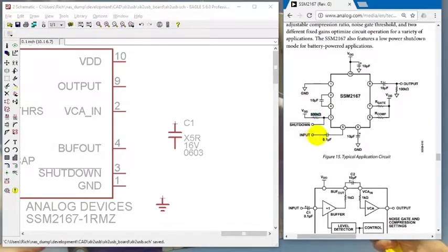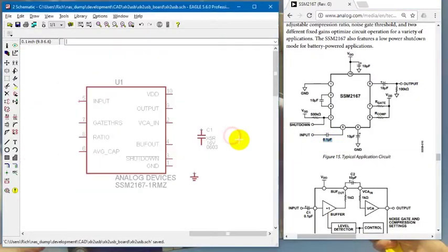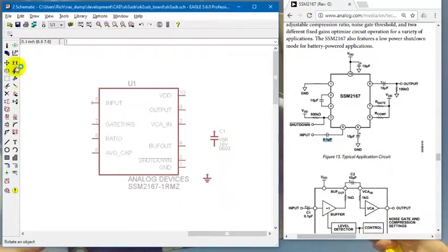Let's hit a couple of more. I want a coupling capacitor on the input side, which is pin 5. And I'm gonna cheat a little bit, and I'm just gonna copy this guy, because I'm gonna use the same size one. And this will give me an opportunity to play with a couple of other functions in here. And one you've probably heard me talk about before, called smash.